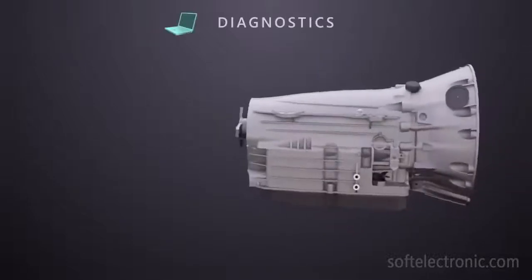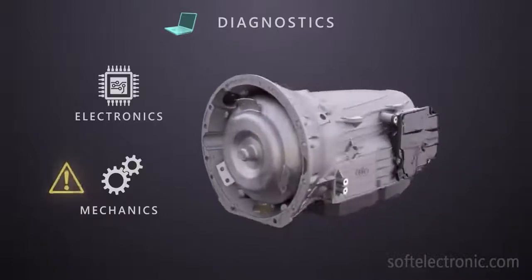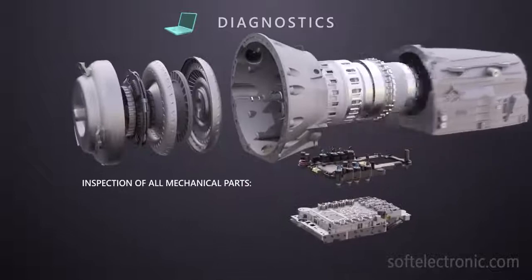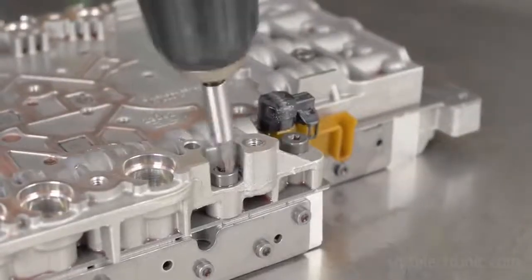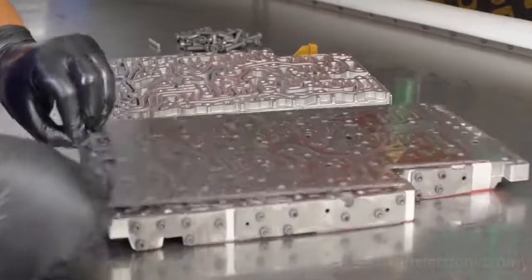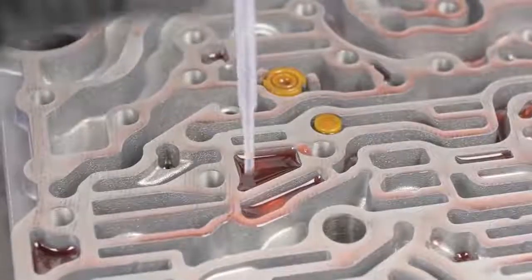If a mechanical defect in the automatic transmission is determined during the overall diagnostics, the mechatronic is then scheduled for dismantling and inspection of all mechanical components, which includes the valve body, gearbox, and torque converter. The valve body is sent to the specialized department for maintenance, and if needed, a repair is carried out. It's disassembled into its composite elements, and after that, a test for the presence of antifreeze in the transmission fluid is performed.